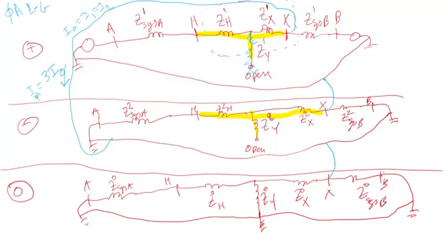So you can ignore it. Assume it does not exist. So what you have in the positive sequence, you have this impedance plus this impedance, since this here is connected to ground basically. So you have these 1, 2, 3 impedances in parallel with this impedance. And the same thing, this plus this is in parallel with the system B negative sequence impedance. You can assume this really does not exist because it's open.